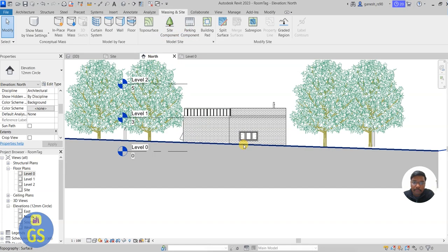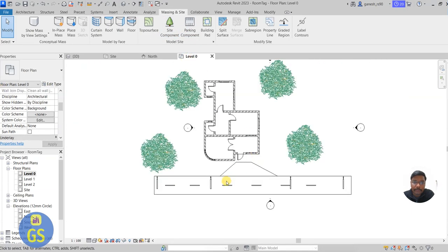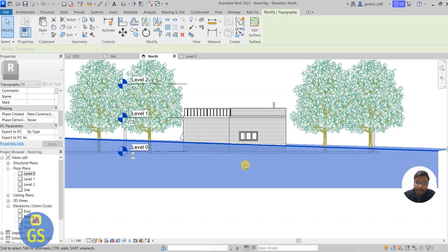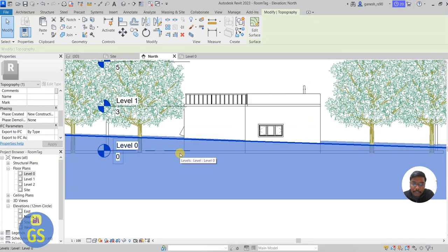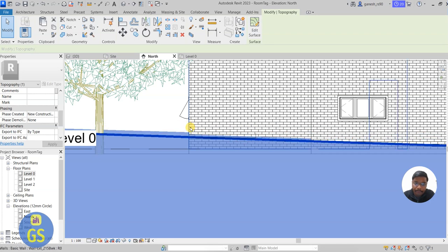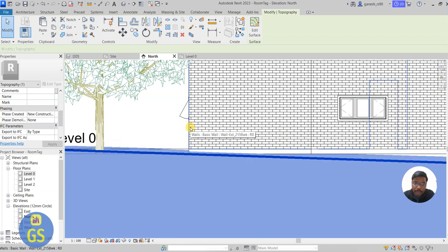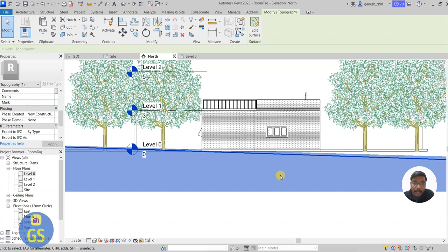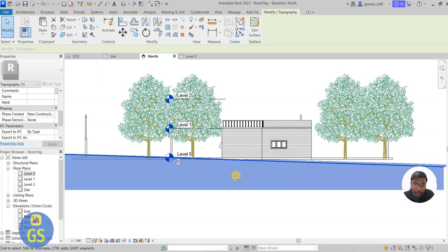Okay. So again, what we want to do is make these corrections. When you work with this correction, we want to do it at the lower level. Since we have given the different elevation points, now we can see clearly there is a difference in this height. When you move down, you need to move down to the floor level, but when you see the other side, this is different. This is the reason, because we have given a different elevation point for this particular topo surface. So this is something different from the previous model, right?